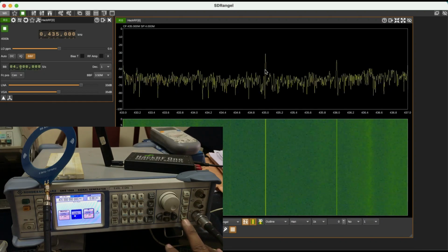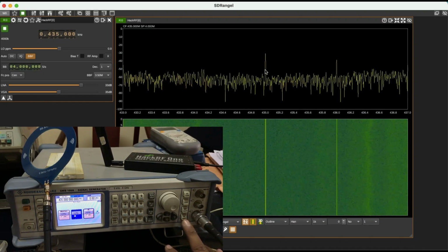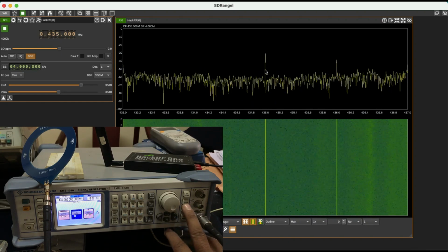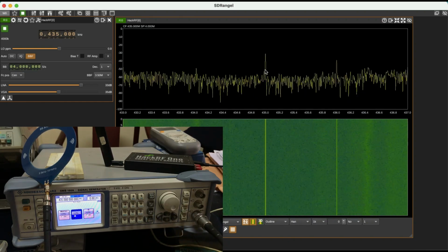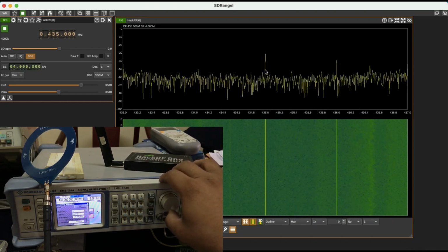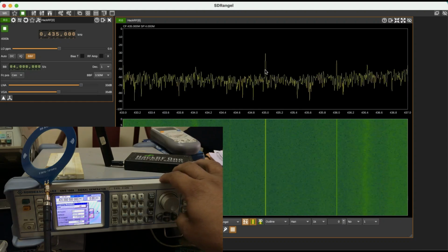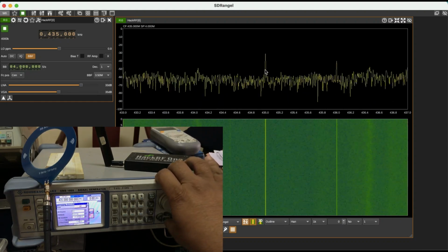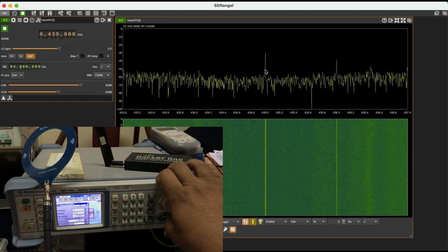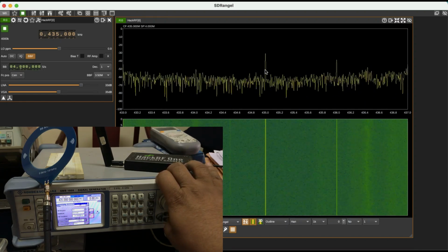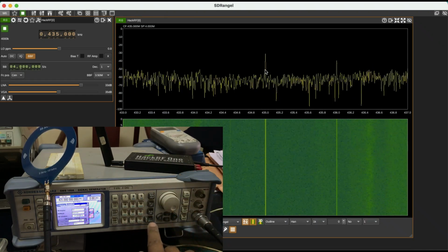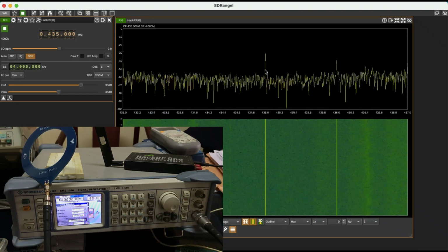It's just the modulation is on, but it's not being transmitted. Similar way, I can do the same thing. I can go to my diagram, go ahead and select this to be an FM. I'll do exactly the same thing. You can do frequency deviation for FM is about 75 kilohertz, and I can choose this frequency FM internal source to be 1 mega. That's the maximum I can choose, 1 mega.